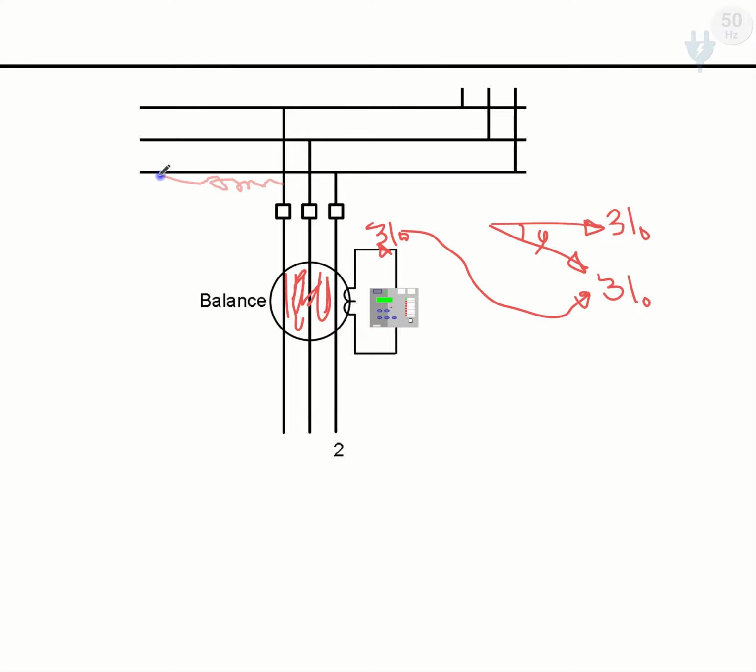Or maybe due to our system configuration, our system is not directly grounded. Maybe our system is grounded by a coil, as for example a resonant grounding coil is used. Due to this resonant grounding coil, during the fault a very high reactive power factor will be present in the system, so our active power factor reduces much.